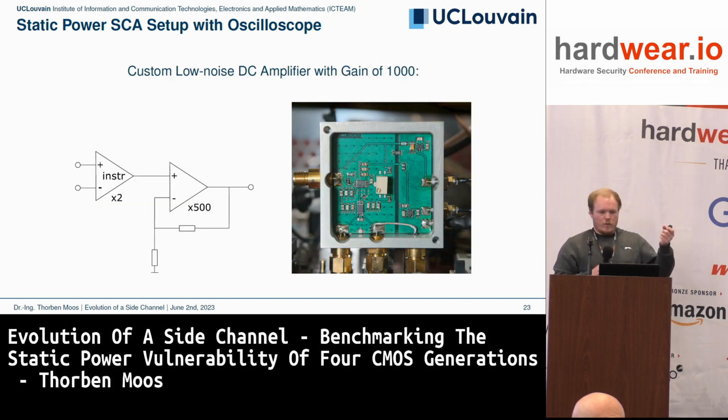One of the ideas was that we have this low noise DC amplifier, which is also temperature resistant, directly on the board, so that we don't need to carry non-amplified signals over long cables in the setup, so that it's directly amplified and then transported.